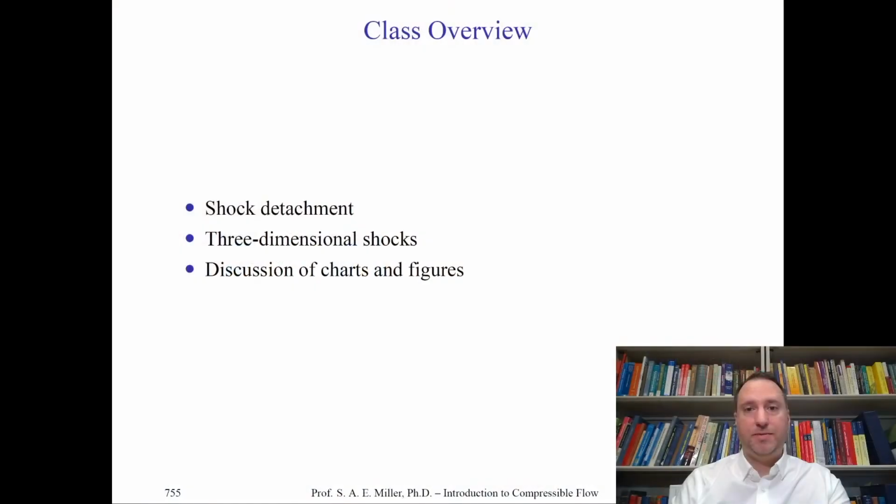Today we'll return to our module on oblique shock waves. First, we'll look at shock detachment. That's the case, of course, where the shock has detached from the turning angle or the particular vehicle or plane of symmetry, and it's moved upstream. This is where, of course, we do not have particular solutions of the theta-beta-Mach number equation.